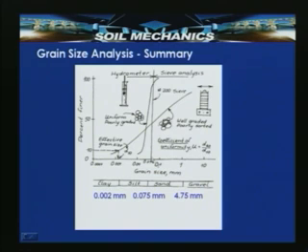In summary, let us look into it. We have seen that coarse grained soils, greater than 75 micron, are analyzed using sieve analysis, where the soil mass is placed in a series of sieves and subjected to shaking. By measuring the percentage retained and calculating the percentage cumulative weight retained on each sieve, the percentage finer can be calculated and plotted. Based on that, different coefficients can be found out, and we can say the soil is well graded or uniformly graded.